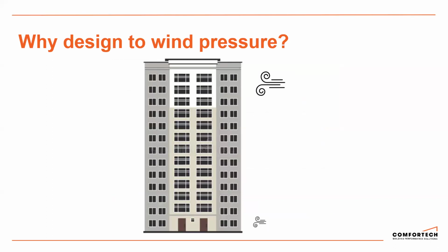So further off for that, why are we designing to wind pressure? Designing internal partitions to allow for different wind pressures is something that has become more prevalent in the last few years. Previously, it was all seismic. There wasn't the focus that there is now on partitions. The reason for the change is now we're building up a lot more. We've got large towers, especially in Auckland, 50-story apartment buildings.